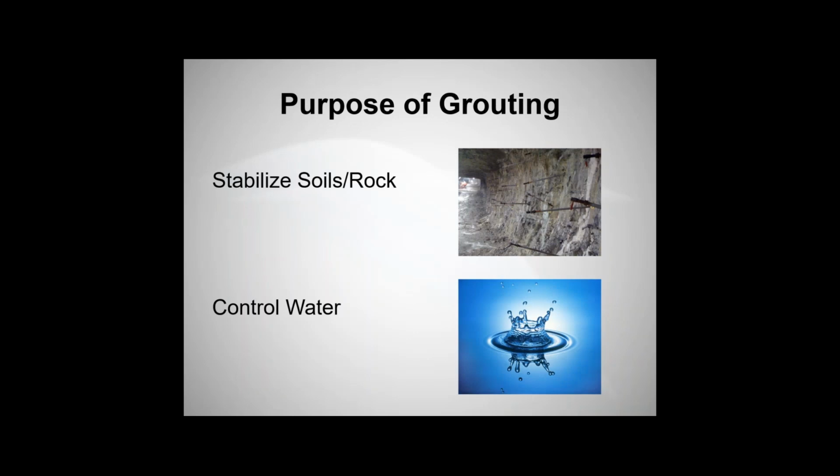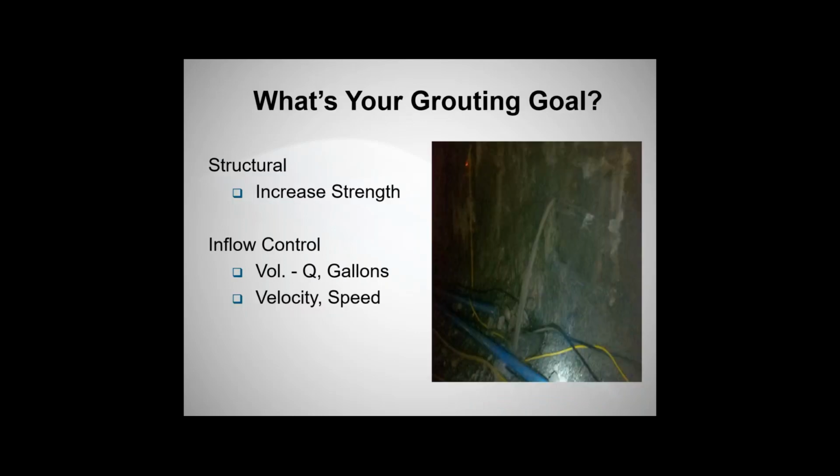We're talking about grouting, and the first thing we need to define is what really is the purpose of grouting. What's the goal of grouting? A lot of times when we're thinking about grouting, it gets looked at from a lot of different perspectives, but maybe it's in and around a tunnel, or it's in and around a shaft, or on a smaller scale, they're buildings, or they're walk-through tunnels, things like that. But the purpose of grouting really can be boiled down to two primary goals, and that's to stabilize the soil and rock that may be in and around those different subterranean structures, or to also control groundwater. It really can be boiled down to those two primary goals.